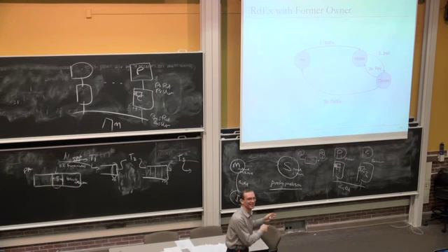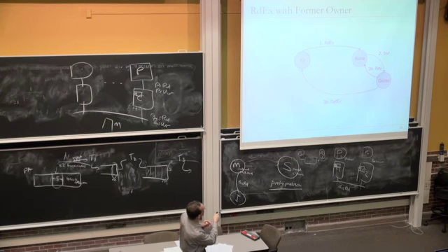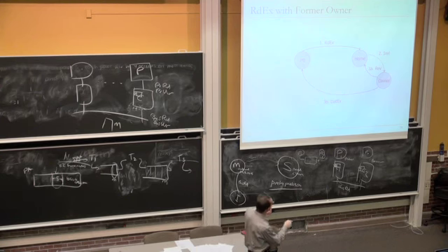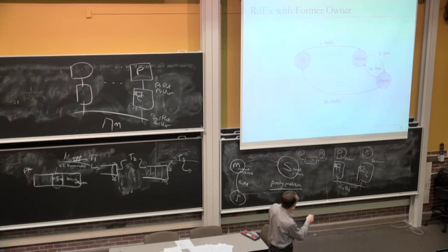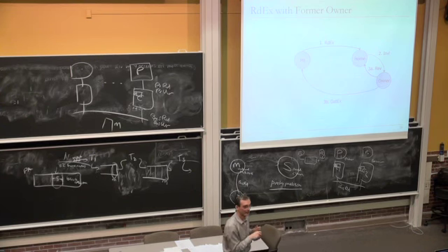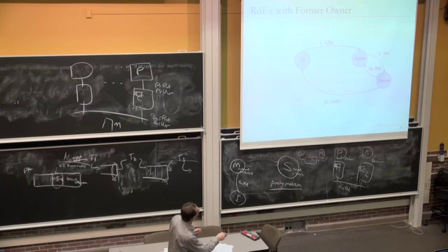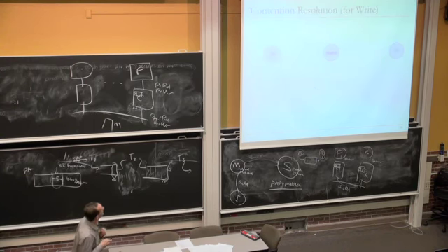And if you have a scalable interconnect, of course, if you have multiple paths between these different processors, the owner, the previous cache or the previous processor that had the block in modified state, can send it to the directory as well as processor 0, and this could go through different paths, right? And in fact, this could go faster than this, depending on how close these nodes are. Right? Okay, so another example, if you will.